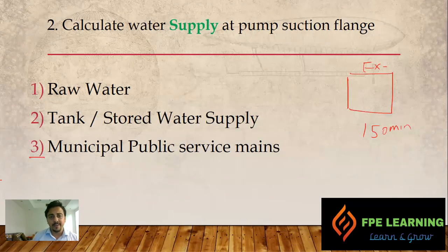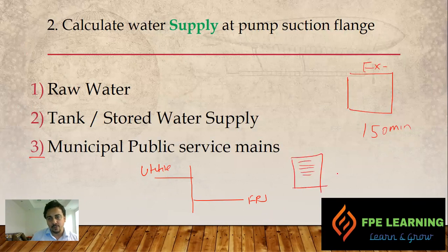So those are the mains that give supply to the fire pump system also, and at the same time they are giving supply to the utilities for various household work. So while selecting those, you have to keep in mind the record of the hydrant flow test is not greater than 1 year. So the maximum validity for that is 1 year. Point number 1. And point number 2 is that those tests are done at the time of the year, 12 month and 24 hour a day, at the time when the demand is maximum.